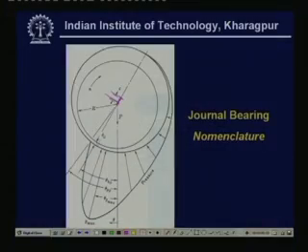This is the minimum film thickness h0, its location, and this is the p max measured from theta. Note that this particular pressure is shown only for the positive part of the bearing, where you have the converging zone. The negative part has not been shown in the picture, because that is not of our use.